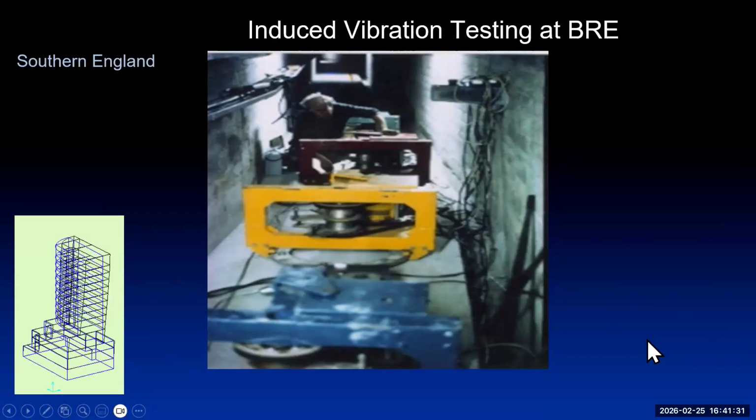And we used that on dams especially, but also, you can see on the left-hand side, there is a building vibrating in its fundamental mode of vibration, and it's excited by a vibrator system like this. And we actually did that sort of thing on Ronan Point. Ronan Point had a progressive collapse, which is quoted in ASCE 7 as well. And I did it using this system that you're looking at now.